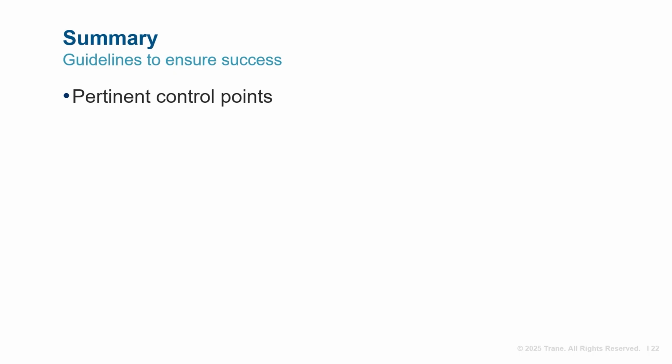Let's wrap this section up. To ensure project success, take care to think through the control points required to achieve design intent. Sidestream heat recovery control is simple and adapts well to changing load conditions. Depending on the application requirements, preferentially loading heat recovery chillers may be suitable.